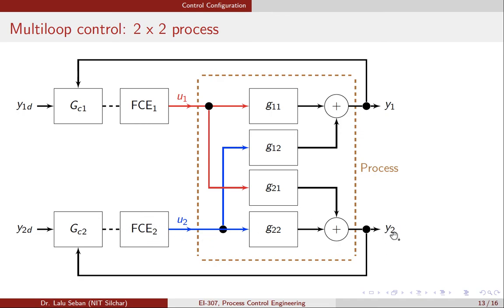You need some manual control here. You can correct the problem in this particular loop, come back to the closed loop, and run the plant. You should not worry about the remaining loops. The remaining loops will run automatically by the controllers.